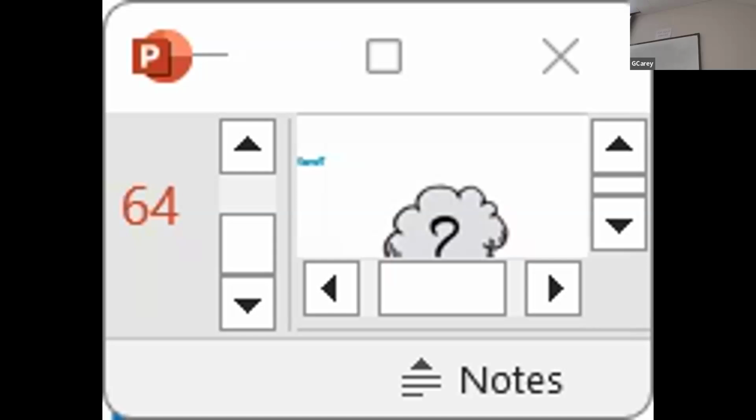You can have a couple of different scenarios. This is saying maybe 100% open to the terminal unit, so that flow is not going through the bypass. It's all going through, so that port there would be closed. All the flow's going through the terminal unit. If you were satisfied at set point for whatever reason and you close that port, now all the flow's going through that bypass. So we'd want to make sure that balance valve simulated that pressure drop to achieve that same volume of flow. Again, waste of pump power, so to speak, but operationally, it didn't affect the control valves negatively.